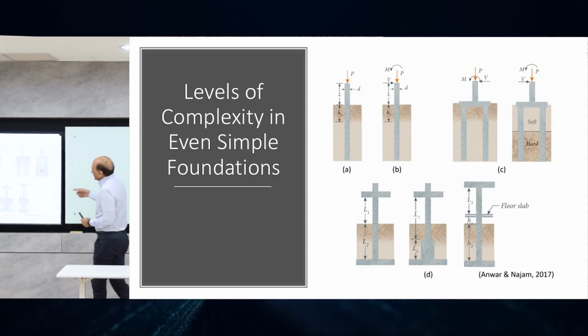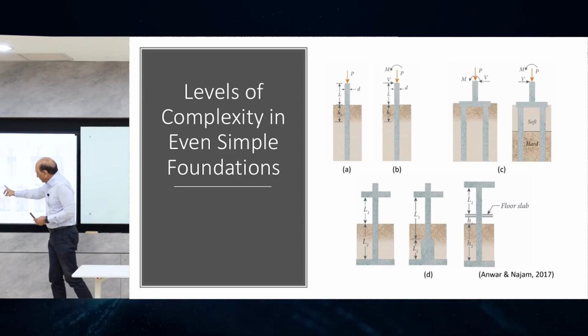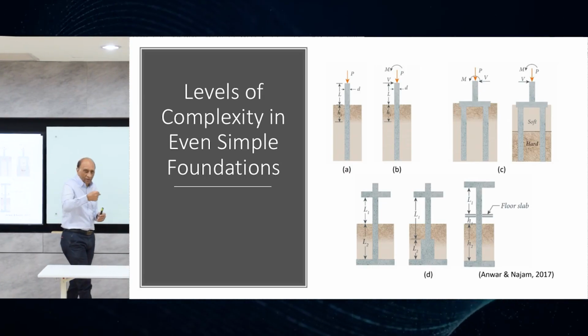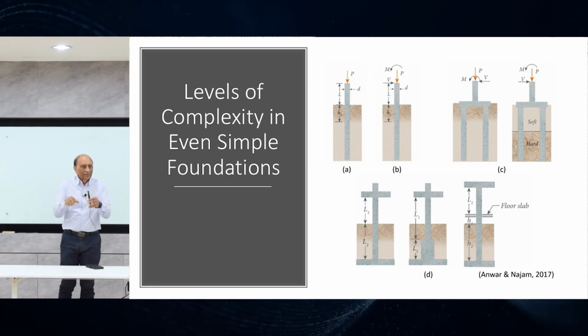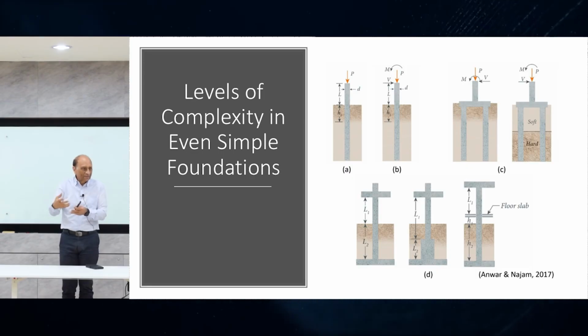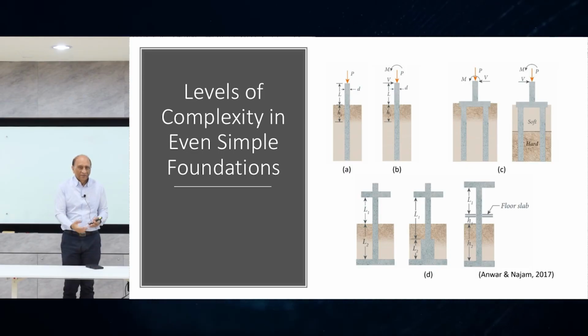And then you have another case: a simple column, you take the foundation down and then you fill it up again. So whether the soil is holding the column or not, whether the footing is free to rotate, what about the weight of the soil on top of that? What is that doing? What is the pressure it is doing? So the whole system suddenly becomes not easy to see how it's going to behave.